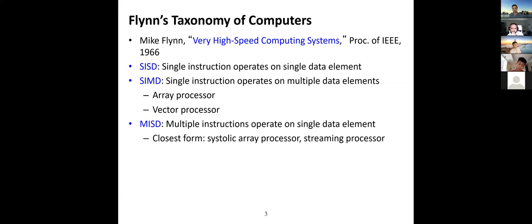Those tensor processing units are built on systolic architecture. And pretty much any other fancy startup that claims to do machine learning hardware right now uses systolic array architecture. It's quite old. It was invented back in the 70s, 80s. It was never actually used so actively until machine learning and matrix multiplication in particular became popular.